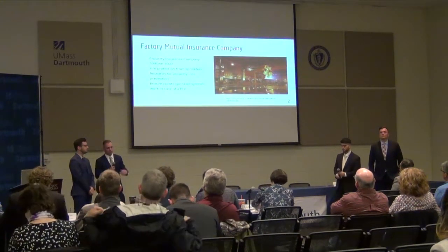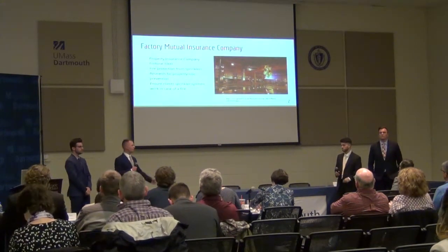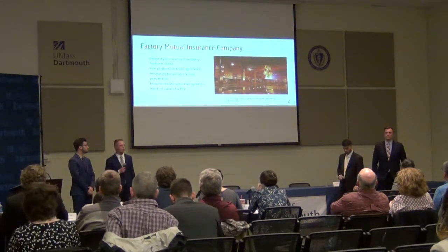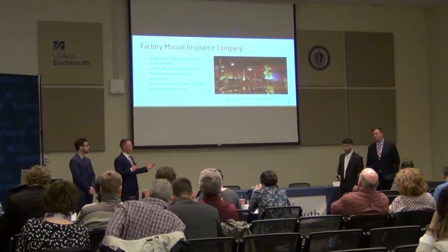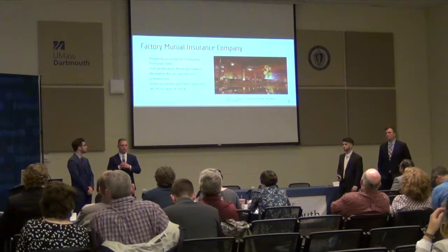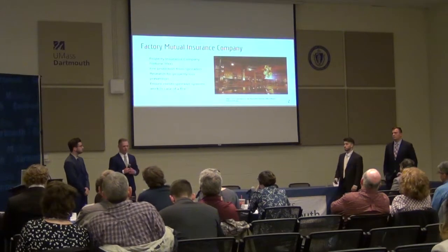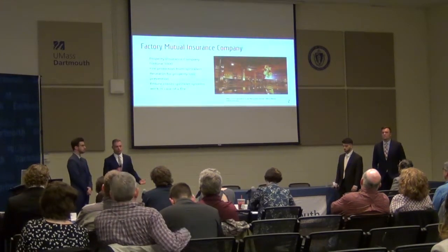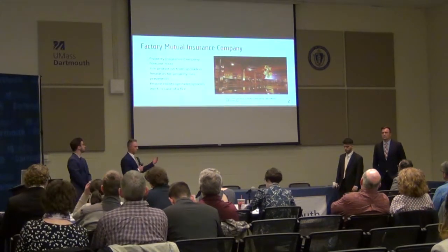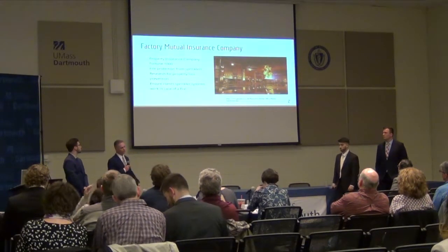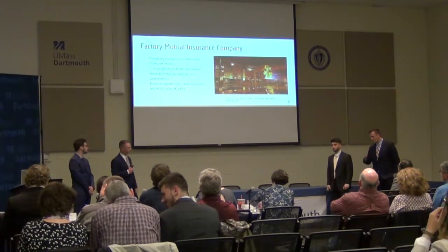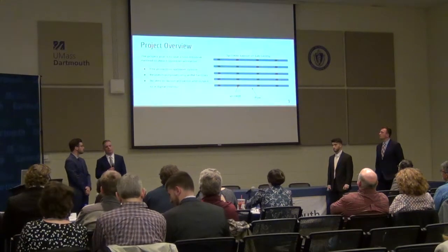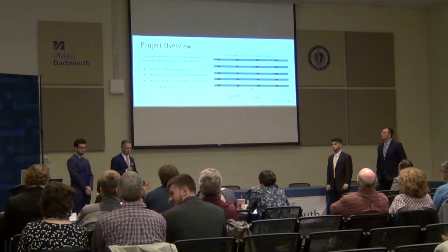For this specific project, we're dealing with fire protection. The picture on the right is from one of their labs at their research campus in Rhode Island. What they do here is they'll set up an array of commodities to burn, run a burn test, then the sprinklers will activate based on how that fire burns. Then they can know, all right, the sprinkler system works or it doesn't work, and that helps back their insurance.